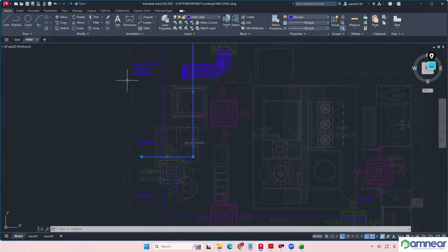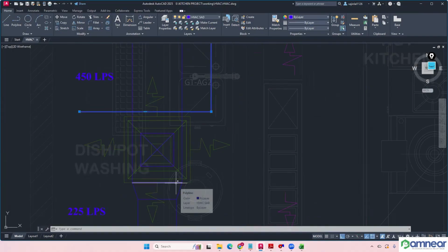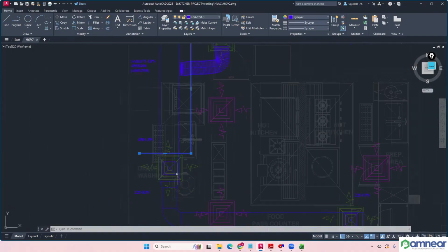But after that, actually the clear internal dimension we need is 400 by 350 only. If you provide acoustic lining only up to here, it will be affecting the velocity. Even so, the duct dimension we are not decreasing. So if you extend the acoustic lining up to here, that will be fine. Otherwise, after this the area will be slightly increasing.